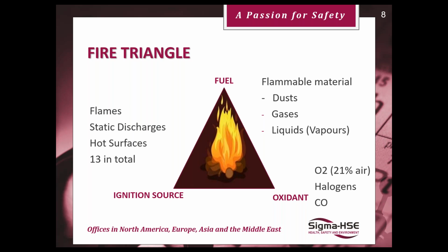Any ignition source can give that sufficient energy to ignite that fuel and oxygen, to kick off that combustion reaction, the reaction of the fuel vapours with the oxygen. We need to impart energy. And because the oxidation reaction is an exothermic process, it gives out heat, and this is where we get our flames and we get the fire and the explosions that we all know and love.